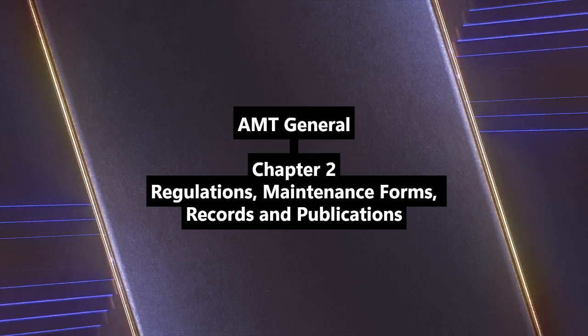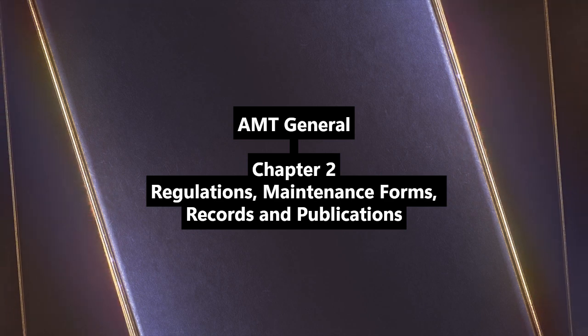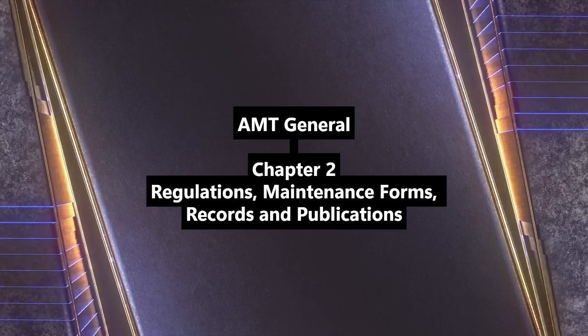Which brings us neatly back to records. Making those maintenance record entries per 43.9 and 43.11 is non-negotiable. Retention rules are in 91.417. Good logs are vital for aircraft value.